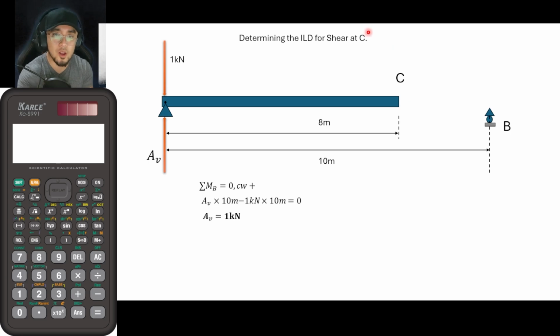So since we are only particular with the shear about that point, that is what we actually need. Again, like what I have said earlier, in order for us to get the shear about this point, VC, or the shear at C, is basically equal to the summation of forces vertical, considering that if we would be cutting a section here, we would only choose one direction, and that direction is the left side. Okay? So, don't mind this right side here, guys. We're only particular with this side.